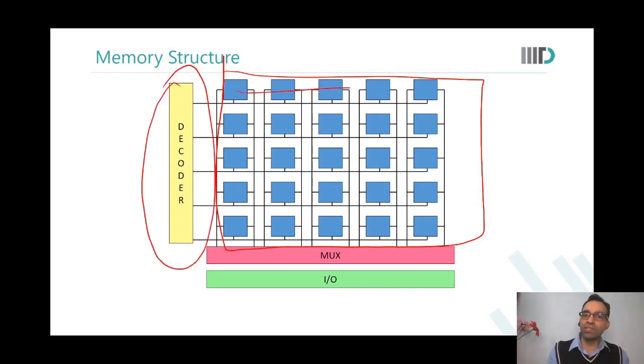If, let us say, we are storing one word in this particular row, then we have a decoder which would select a particular word, and we have IOs which would give out the output. So by putting them in a structured array, we are able to make the array much, much denser, and also use lesser periphery circuits or lesser additional circuits than what you would use in a latch.